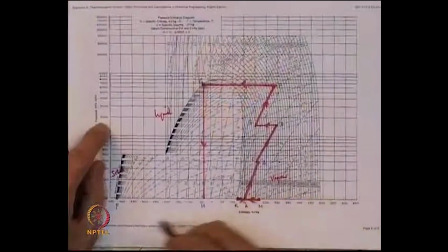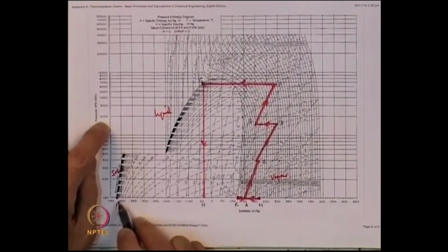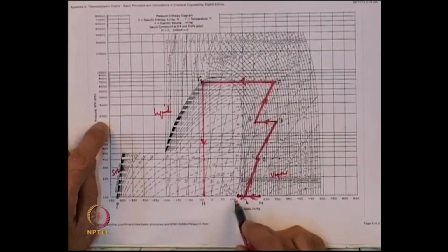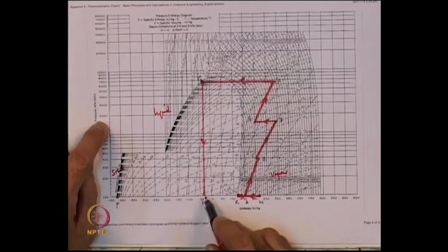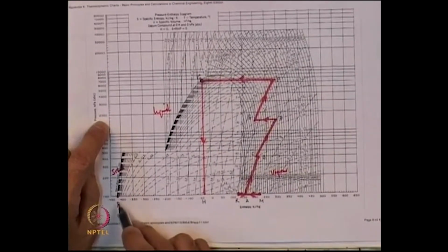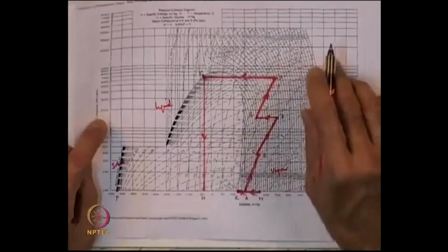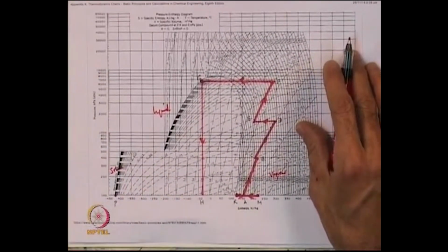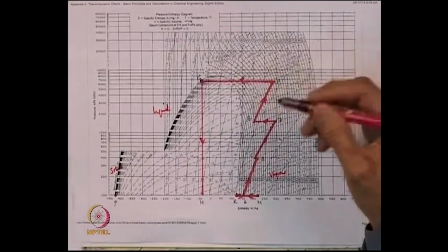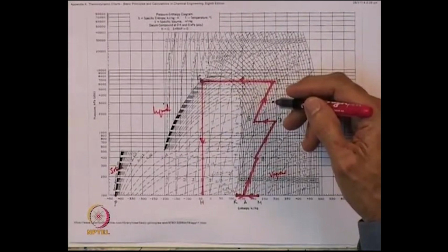So, the recycled, you can see on this chart, you can see where the recycle is and where the product is. You can see that the product enthalpy, which I read out for you, is minus 420. The enthalpy of the saturated vapor at 100 kPa is 120 and H is at minus 40. So, you come to the conclusion that the fraction of solid produced is 0.31. So, that completes our analysis of just the throttling operation and the separation into product and recycled vapor.